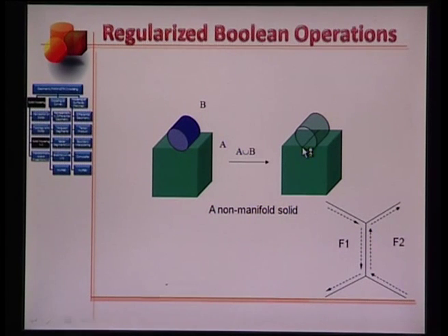If we look at this common edge, this will have, as I mentioned before, 4 faces and not 2 faces associated with it. So corresponding to this edge, the winged edge data structure will complain, and we can detect that complaint, and we can say that this solid is not a valid solid.